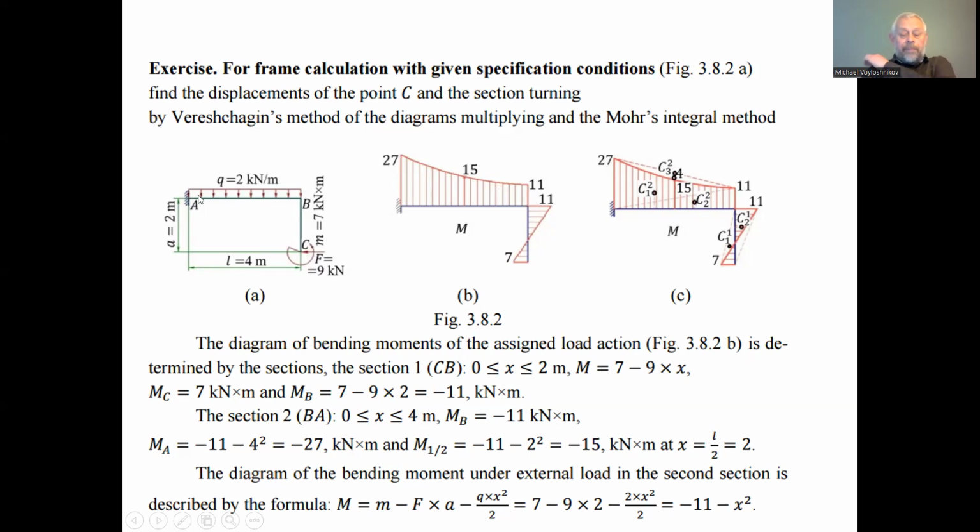And we can find that here the magnitude of the bending moment is 27 kilonewton meters, considering everything together. We can use as well the formula from the previous article, that the bending moment here, counting from the point C to the point B and to the point A, consists of the moment applied at the point C, but the moment is a free vector; it can be moved to any other point.